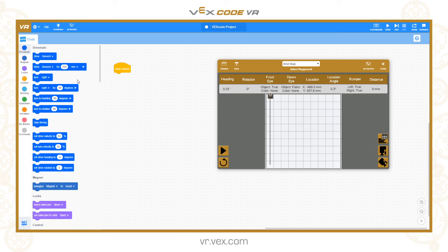So the blocking commands are all the ones that you see with this little white arrow facing out to the right at the end, and the white arrow allows you to change that command to "and don't wait." This makes it non-blocking. Now be careful how you use that and think about the logic of it before you use it, because if I was to, for example, we talked earlier about the stop driving command. So if I say I want to drive forward 1000 millimeters and use the stop driving here.